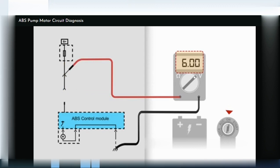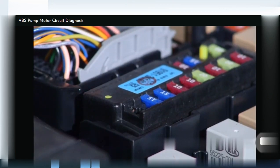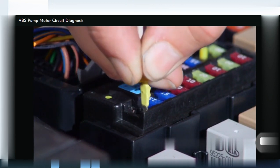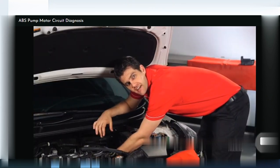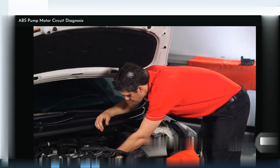If while testing, correct voltage is found after a connector, inspect the connector for corrosion and terminal tension. If the voltage at the fuse is low, the resistance is in the circuit to the fuse box. If voltage supply to the fuse is okay, confirm the fuse holder terminal tension is correct. If voltage supply tests OK at the ABS harness connector, check the module for corrosion and terminal tension.